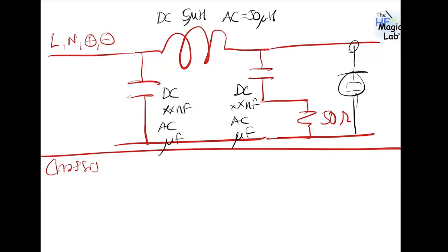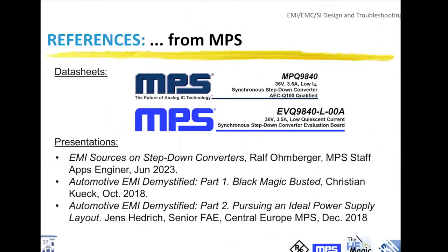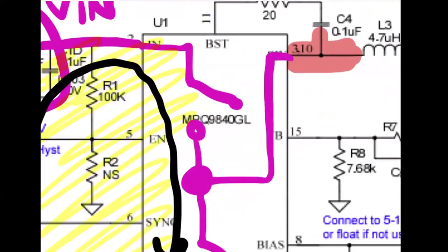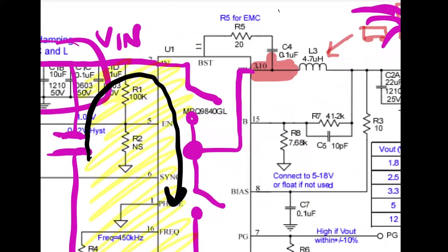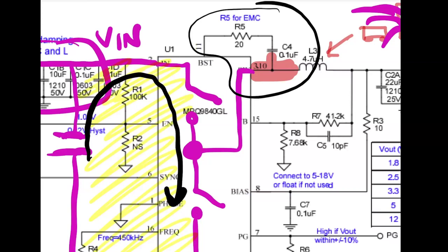Great. Next up, C4 and R5 appear to be snubber circuits. Do I need to place this on the same side as the IC? Okay, I suppose they are referring to this one, this area here. R5 and C4, you can work with them for the EMI, but be careful, because the efficiency of the converter will be very related to the values of these components. Anyway, as you say, these components must be exactly in the same layer as the components of the IC.